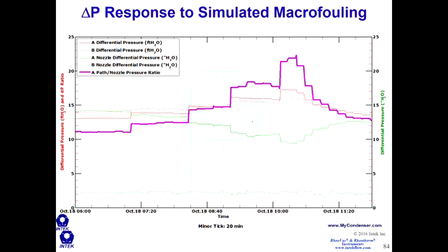But it does require some know-how to install the DPs to make sure that the taps remain unobstructed over time, and then to calibrate if you want the actual number of tubes obstructed. And so we talked about how to make this tap, how to locate these taps, and how to install these taps to avoid some of those maintenance issues. We talked about that yesterday.